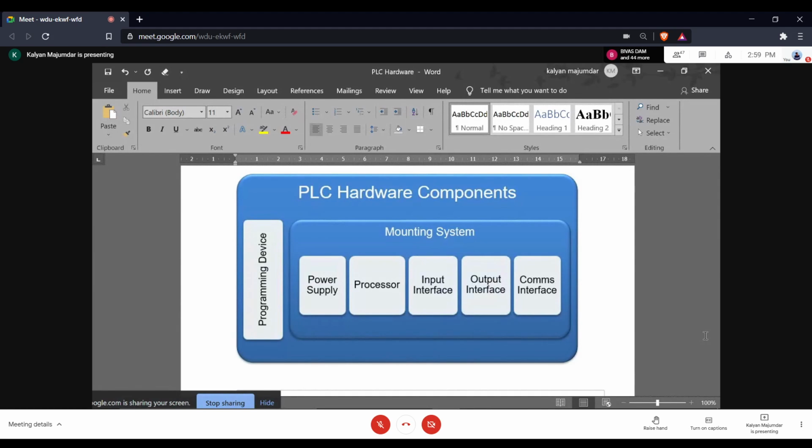Plus, in a physical PLC, what is very important is if there's any hardware fault within the PLC, PLCs are always built with extensive diagnostics. The problem is if your PLC goes down, if there's a failure in the PLC, then your plant goes down, your machine stops, your equipment is no longer working. And in a factory, if your equipment is not working, if your process is not working, first of all, you have downtime, that is, you have economic losses, but there could be many other dangerous consequences if it's handling dangerous materials, for example, in petrochemical plants. So their failure is simply not acceptable, right? So you need extensive diagnostics.